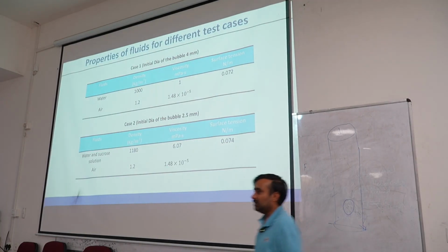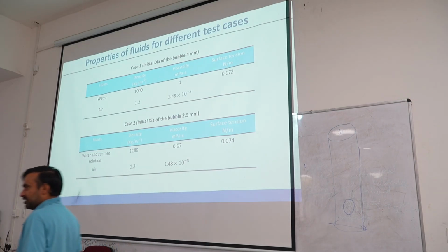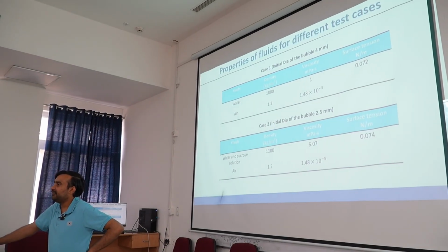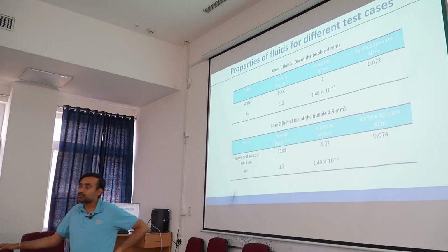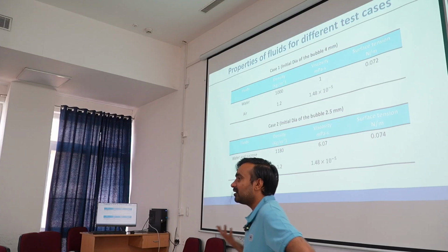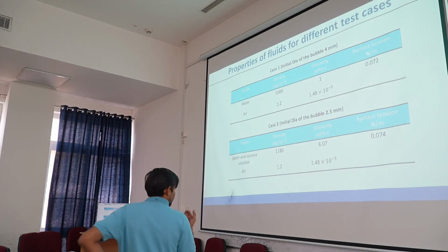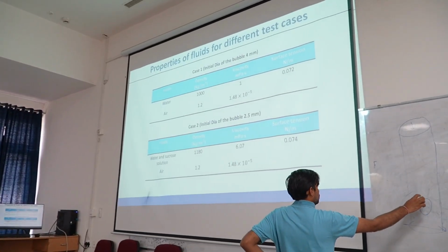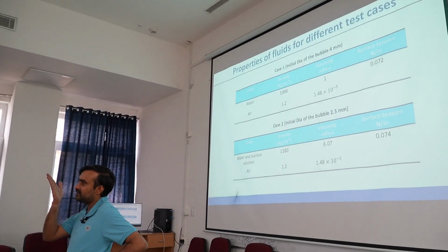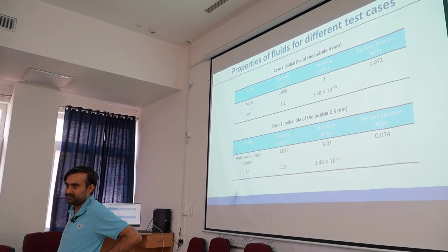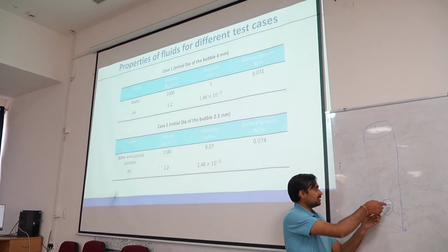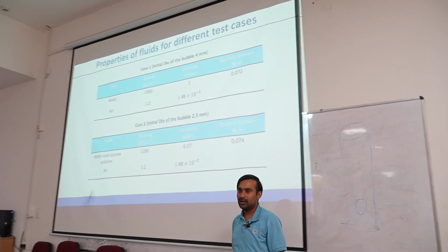Numerical simulations require a significant amount of time and also involve a good amount of computational resources. Whenever we go for a 3-dimensional simulation, we need to properly resolve the interface, so across the interface we must have a good amount of grid refinement, so that the approximation of the interface is proper. Moreover, I cannot refine only this zone, because the bubble is also displacing in the forward direction.